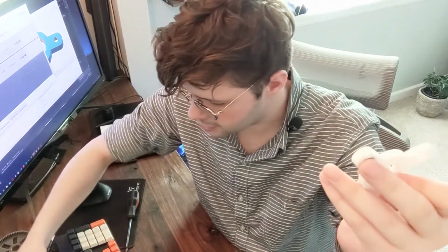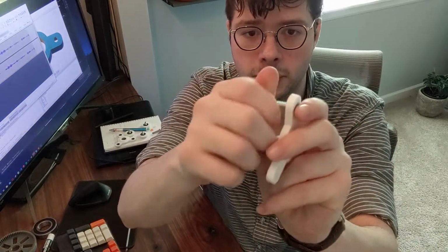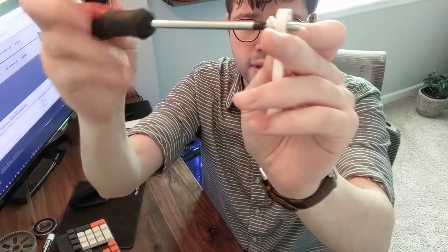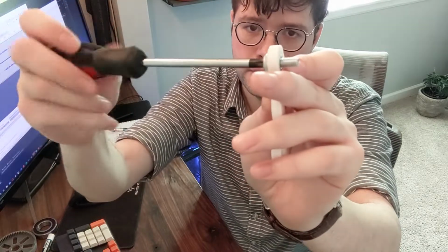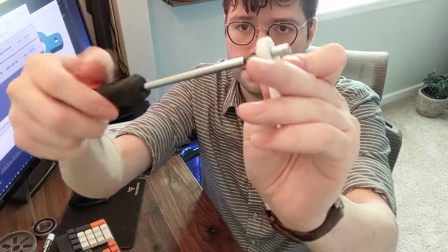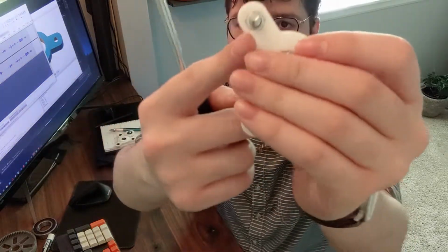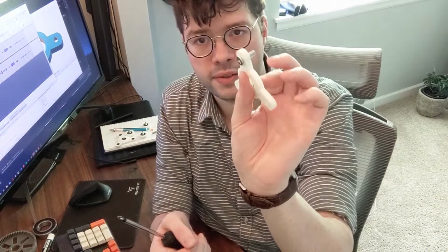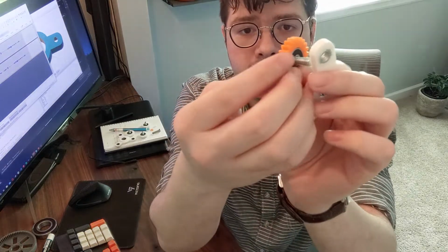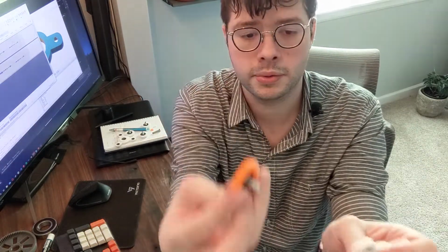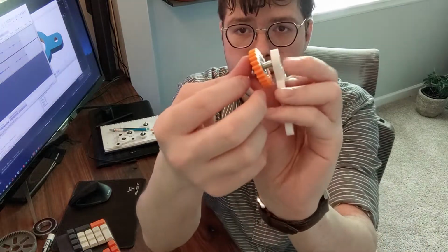And what does this allow us to do? Well, a capture nut will allow us to thread a bolt through the part. Once it got to the end of the thread, the pressure of the bolt against the part would pull the nut and recess it fully into the part. This creates a very tight bond between 2 different parts. So we have this gear and we have this part. And if I wanted to attach both of them together, I would simply put the bolt through the gear and then I would attach it.